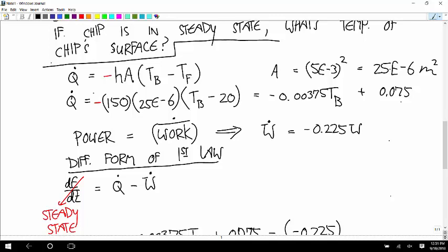But what if instead we were able to measure the pressure in that fluid or the specific volume of that coolant as it went across? If we knew relationships between the specific volume and or the pressure and or the temperature at the state that it was in, we could use the stuff that we knew to calculate the temperature that we needed for that convection heat.